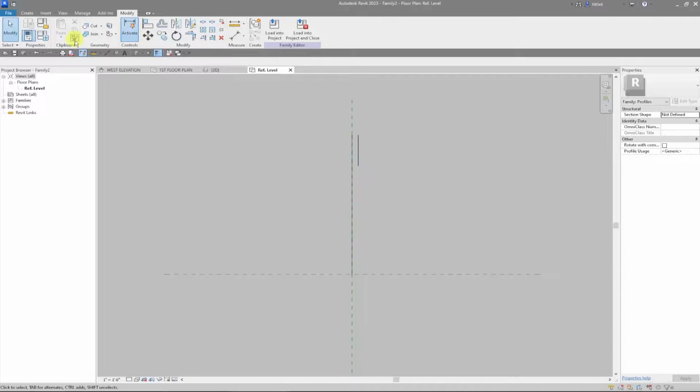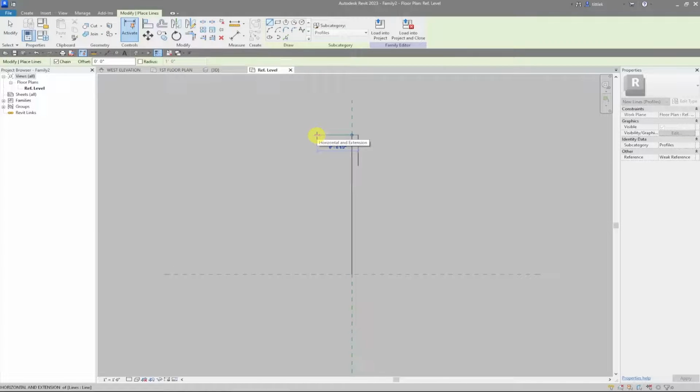So now I can come in here, I can create a line from here over, and the total width of this thing is 6 inches. I can come down here now to this reference point. We're going to come over from the back 1 3/8 of an inch, and then go straight down to our baseline, finish that, bring this over, and then trim this up so that we have a continuous loop.